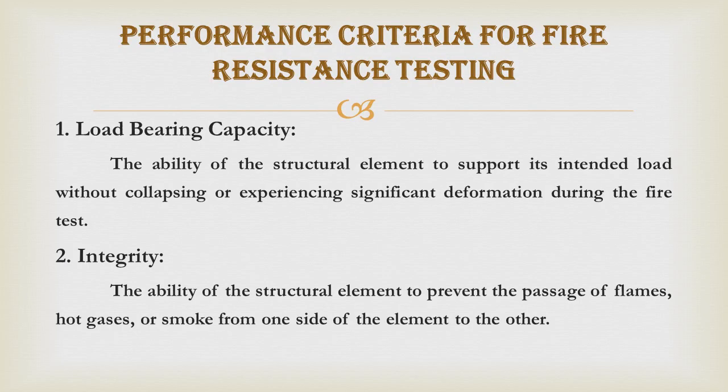Performance criteria for fire resistance testing. Load bearing capacity: the ability of the structural element to support its intended load without collapsing or experiencing significant deformation during the fire test. Integrity: the ability of the structural element to prevent the passage of flames, hot gas or smoke from one side of the element to the other.